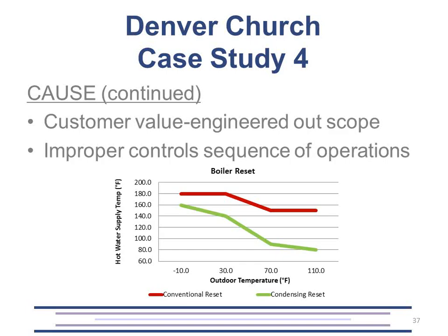Exacerbating the problem was that the two-pipe changeover pneumatic valves were not replaced, after all, due to value engineering. So now the air compressor had to remain, and the valves left in place impacted the required fail-safe operation, resulting in additional costs to correct it anyway. Lastly, the controls contractor set up the hot water supply temperature to reset between 150 degrees and 180 degrees, which is great for a conventional boiler, but will eliminate the savings potential in a condensing boiler application.